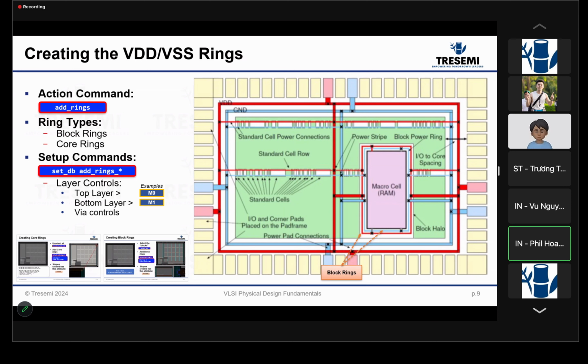Excellent question. I just want to add that typically we would like to have the size of the VDD and VSS the same at the IO pad. It makes it easy to do the planning, and if needed, we can just add more pads, either more VDD or more VSS pads. Typically the highest layer is very thick, and you don't use it for routing purposes. Mainly, you use it to distribute the power.